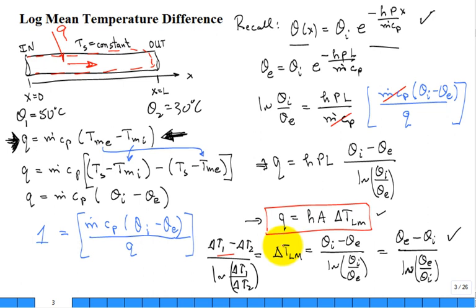If it's coming in the side of a large control volume where I have fluid flow coming in and going out, something's going to happen. It's going to heat it up. It's changing its enthalpy, approximated as C times T, specific heat times temperature. So we have m dot times the change in enthalpy. There you go. It's the energy balance for the whole system.